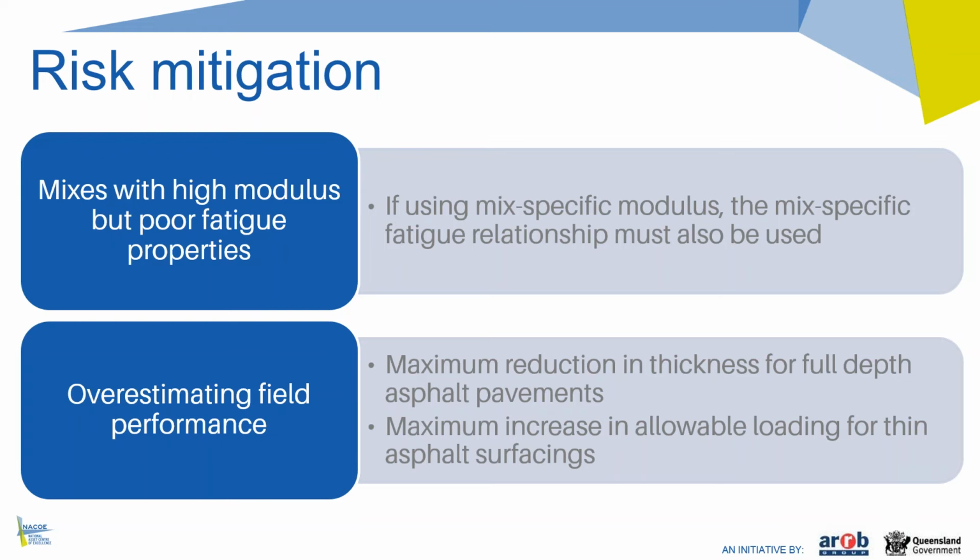So on that basis, the technical note includes limits on the allowable reduction in thickness that can be gained in full depth asphalt pavements using the mix-specific modulus and fatigue relationships. That reduction is currently set at 10%, but we're open to, I guess, discussion about that value.